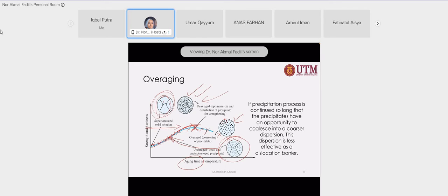There's no barrier. Dislocations move slightly more easily inside the white region. The only obstacle is the solid solution, restricted only by the distorted lattice. The lattice will distort because there is still alloying, there are foreign atoms, but there is no precipitate inside this white region, so there are more ways for dislocations to move. So there is an optimum.